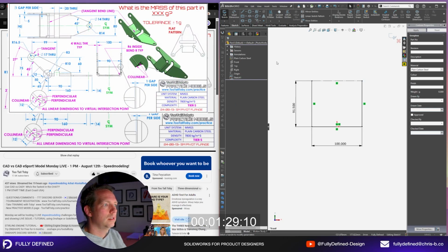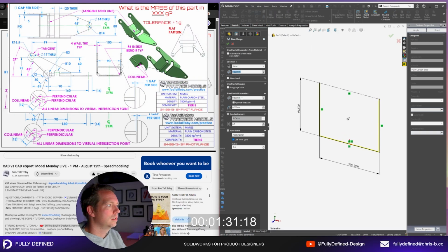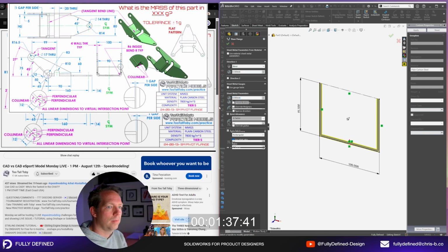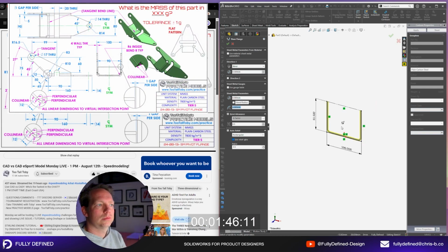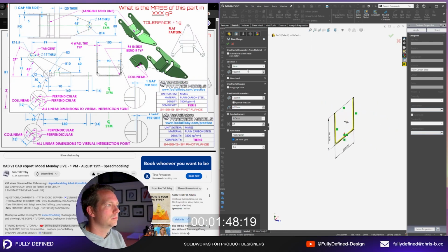You can also see that the 50 millimeter angle flange, thickness 4, running up the back of this part, is directly collinear. Some of the other geometry, the triangular side flanges going up the side of this part, in manufacturing would end up being welded together.